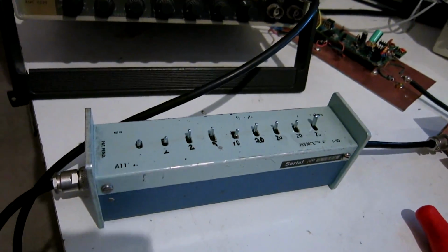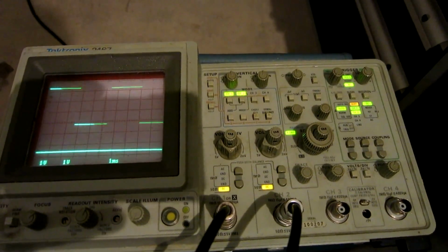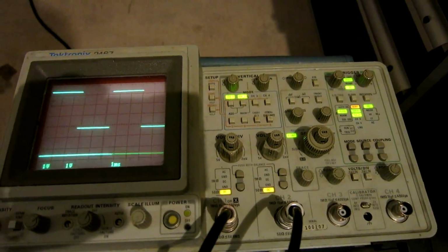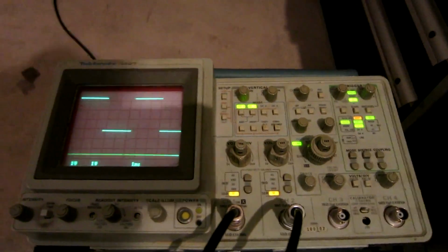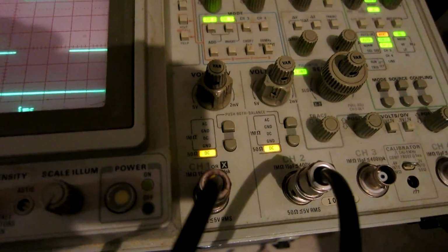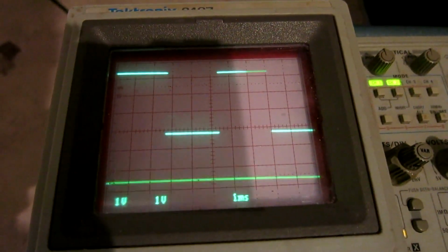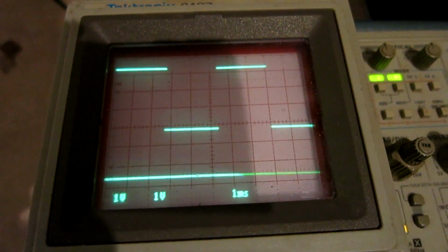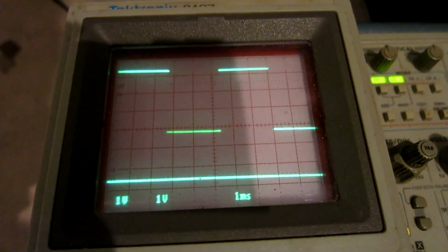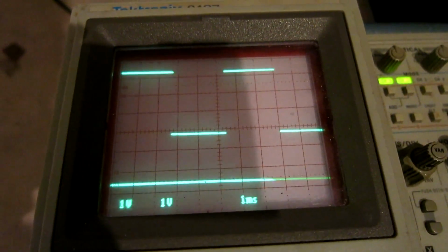With the attenuator here, the signal level is set to give the same signal strength and the same pulse repetition frequency in Linrad. And the input on the oscilloscope is 50 ohms, just like the Softrock on 14 megahertz, where the experiment was done. And the oscilloscope is set to display the two traces, and it triggers on each one.